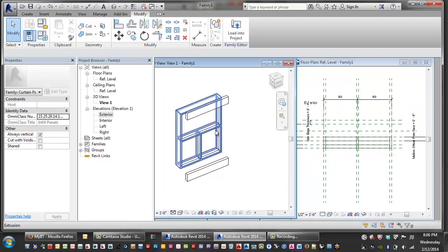All right, so then the second portion of this, now that I have all my data, is I want to go ahead and begin setting up family types. The main family types that are going to get set up are a full panel with everything visible, and then another family type of this that has only the top slab edge cover visible. And then I'm going to have another where only the bottom slab edge cover is visible. So that should handle everything in elevation for me in one family.